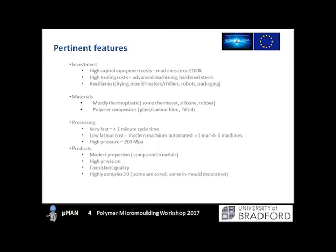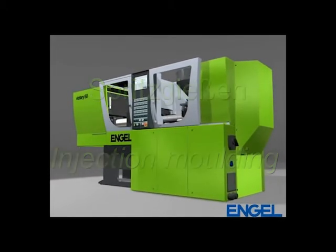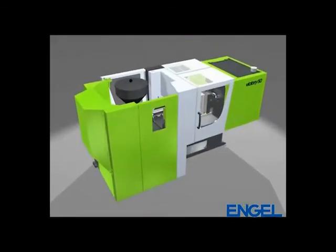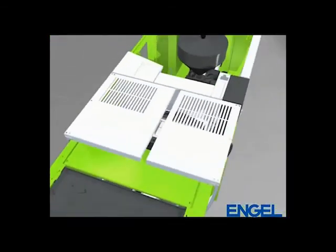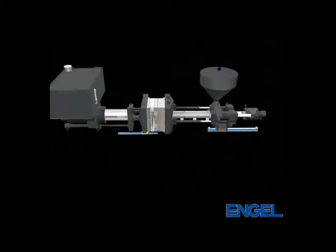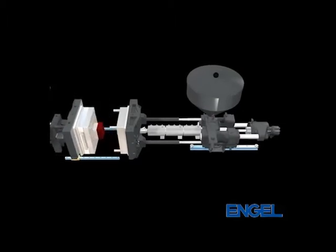So let's have a quick look at how the process works. This is an animation supplied by Engel, who are a company who make injection moulding machines. They do have a nice funky soundtrack to go with it, but it's going to get in the way of my talking. So basically, the machine is split into two individual areas. You've got the plastic melt preparation side, which is this side here, which is going to do the melting of the material. And then here we've got the mould side. So this is clamping the mould together, where our mould sits in there and also has things like the ejector pins that pop the part out of the mould.